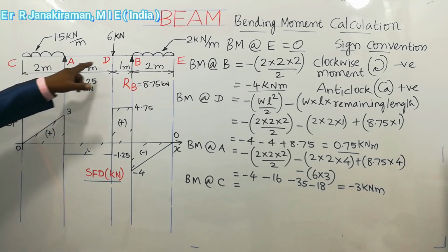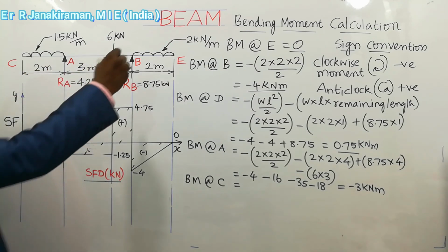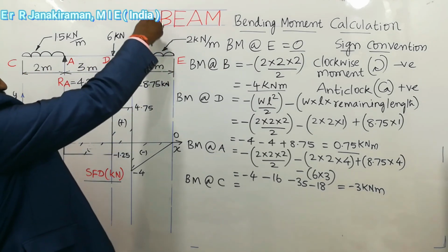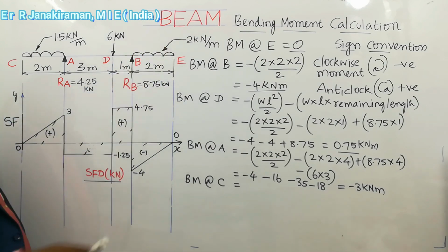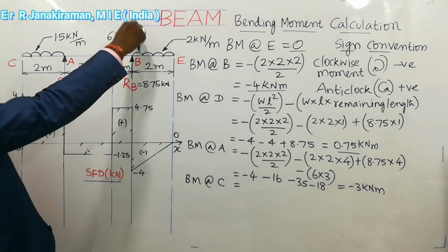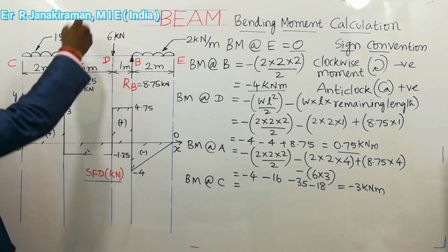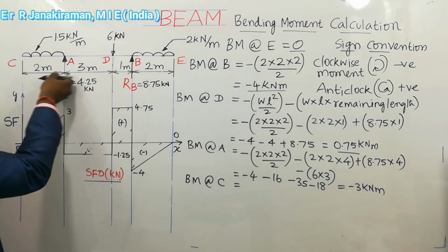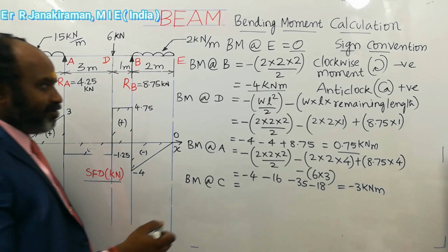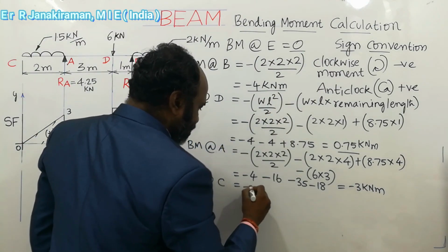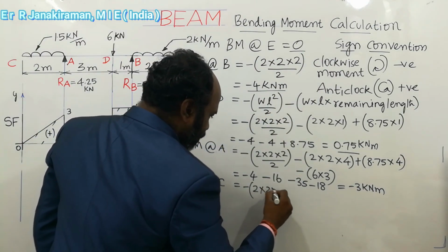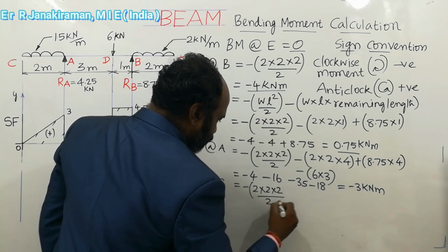All the loads need to be considered. So 2 into, first we consider this. It acts downward, a downward force, that is the UDL load. It turns like this, it forms clockwise movement up to point C. So forms clockwise movement. Clockwise moment we consider negative. So minus 2 into W, that is W L square by 2.